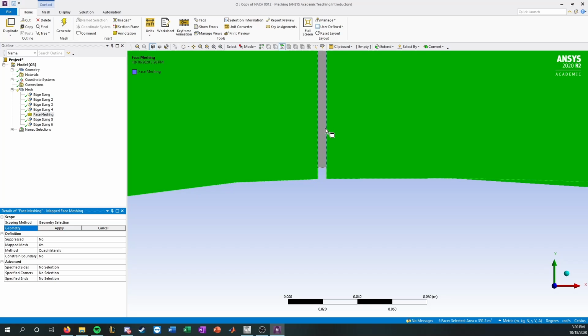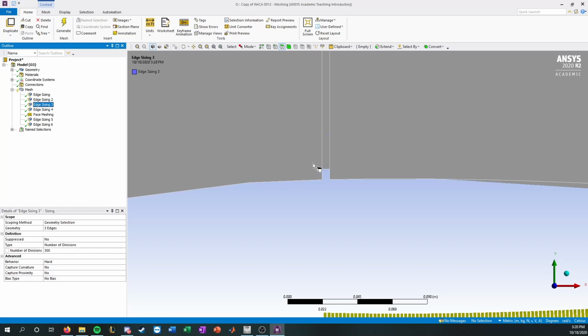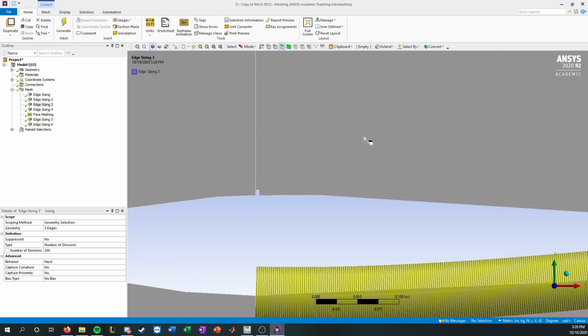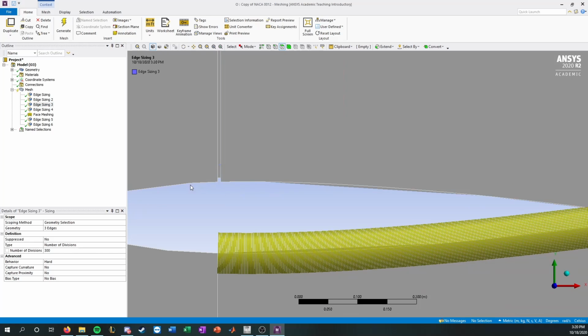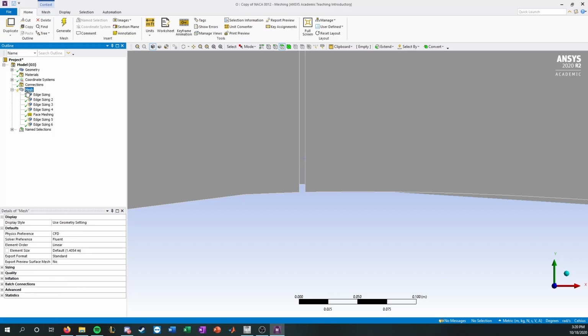Oh, don't forget to update faces. So I changed it to be 300. So there's 300 elements from the very top too. So these two parts, this edge and this top edge, have to summate to 300.